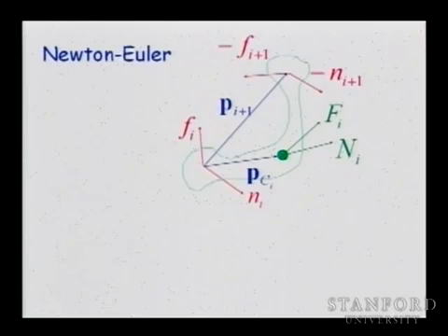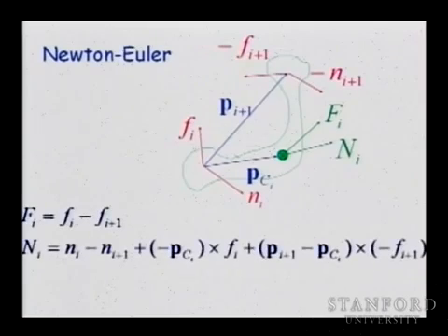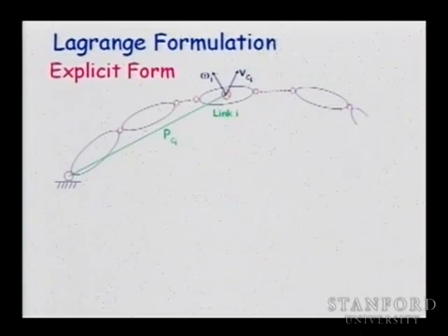forces and acceleration. Well, this way, which is called the recursive Newton-Euler formulation, is going to require elimination of these internal forces and elimination of the forces of contact between the different rigid bodies. And what we will do instead, we will go to the velocities and we will consider the energy associated with the motion of these rigid bodies.